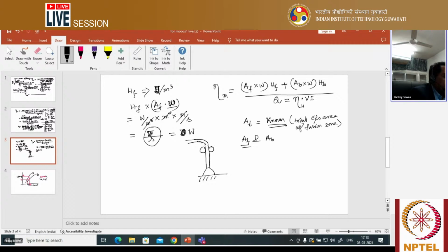So this arc is generally subjected to some wire feeder mechanism. From there, a droplet is forming and transferring. The arc is melting this consumable electrode, and the electrode melts and is deposited. Once it is deposited, by this wire feeding mechanism you continuously supply the electrode, or you can say filler wire.